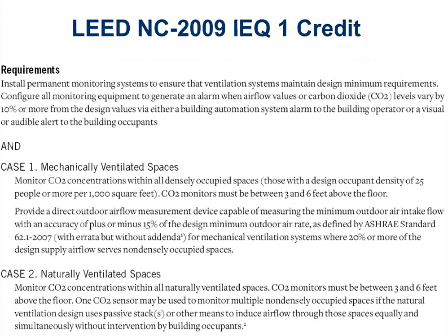If you're doing a LEED project, the 2009 version of LEED, which is still the current one, even though we got drafts of the 2013 out there, CO2 sensors are allowed for EEQ credit 1, but you do have to mount them on the wall between 3 and 6 feet. You're not allowed to put them in the return duct. And they're already triggering theirs based on the 25 people per 1,000 square foot rule.